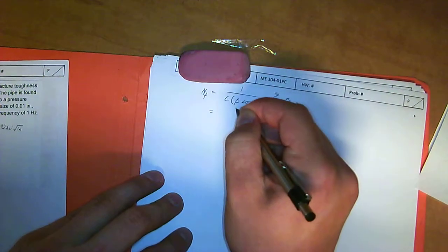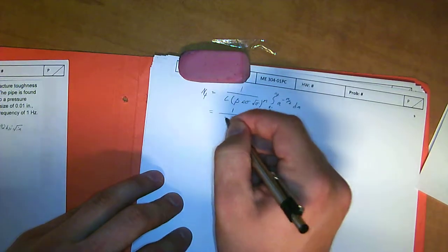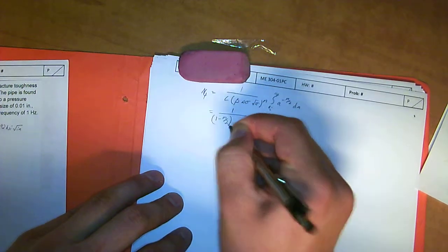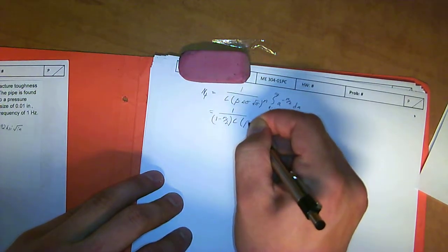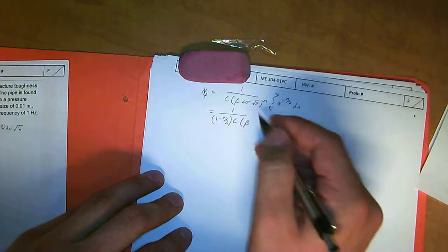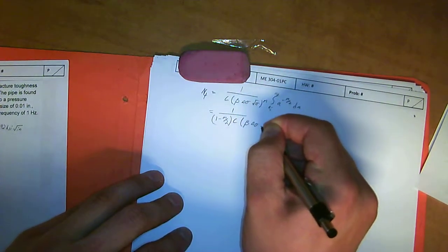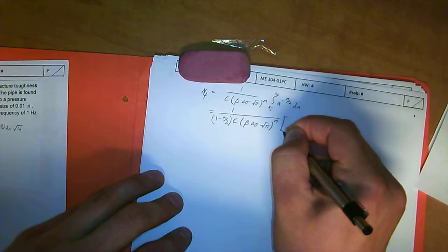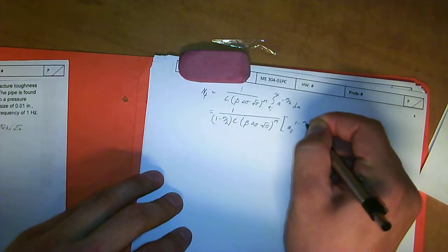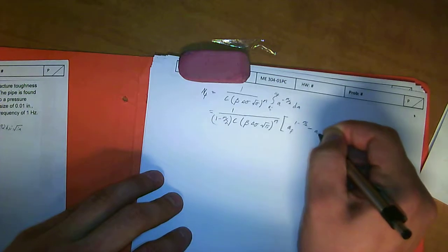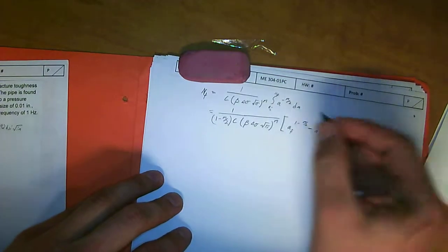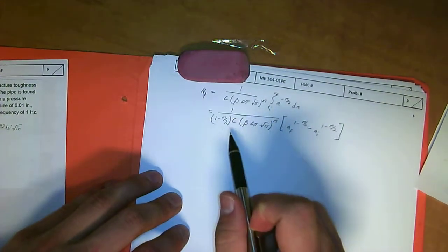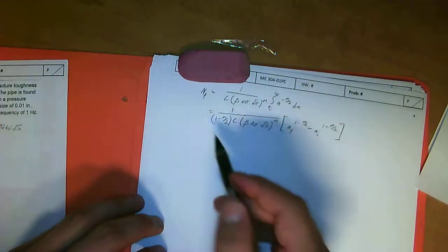Moving on, doing this integral with just the variables here: beta delta sigma square root of pi, to the power of m, carry that on out, all times A final to the 1 minus m over 2, minus A initial to the 1 minus m over 2. So that's doing the integration just with the symbology there. And now you know what the basic equation is. We have an algebraic equation. All we have to do is solve this, and we'll get the number of cycles to failure. And we know the frequency is in hertz, which is 1 cycle per second. So we'll be able to transfer this directly into seconds and then convert it into hours. So it's really easy. But we still need C and we need M.